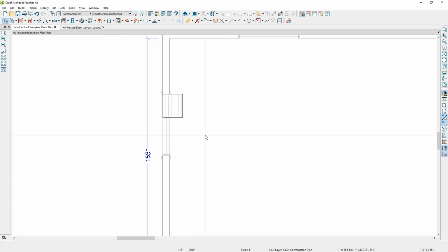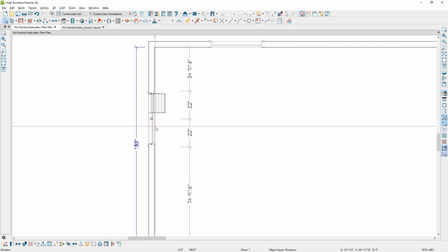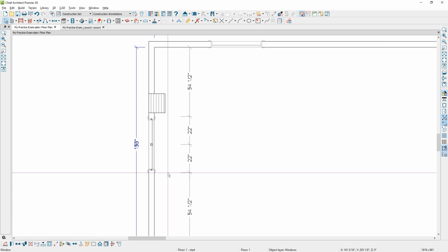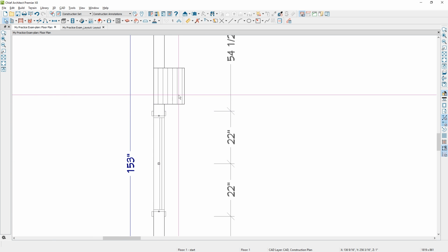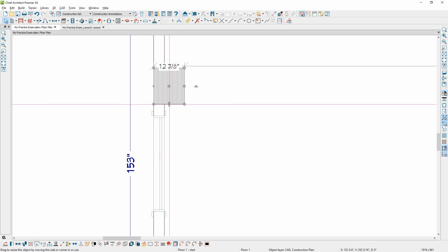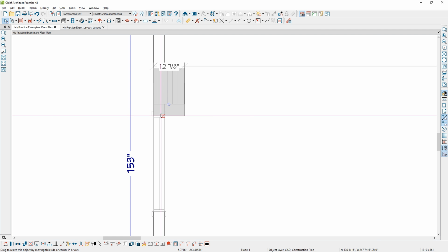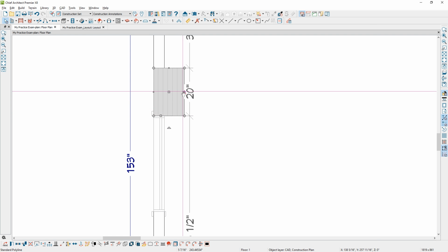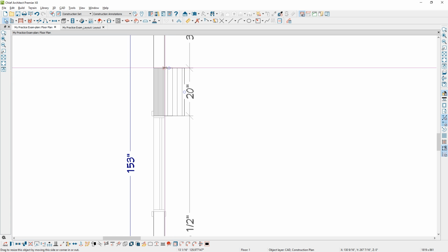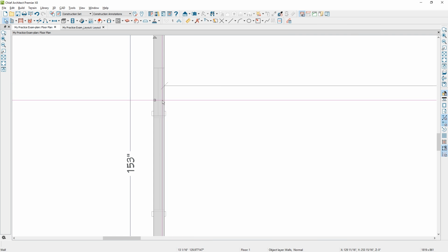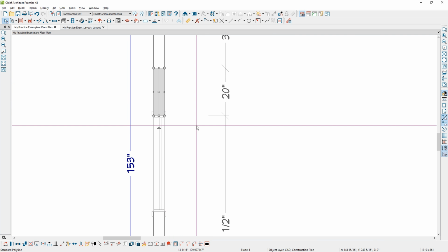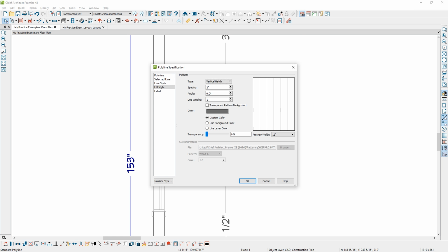Now once I center this window, I'm going to grab the window and use the center tool and center in the design. So now that's centered, and we know that that window previously was at this point in the upper section, and I'm just going to pull this down to where it snaps in to where the new window has been relocated, and then I'll pull that over and snap it against the wall. And you may need to tighten up the fill on that. Let me just click on that. Sometimes you have to press the tab key to get to it,